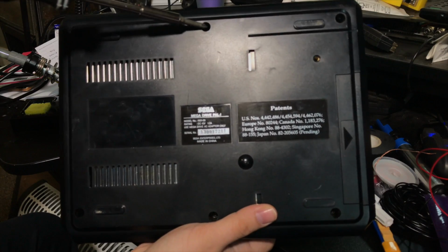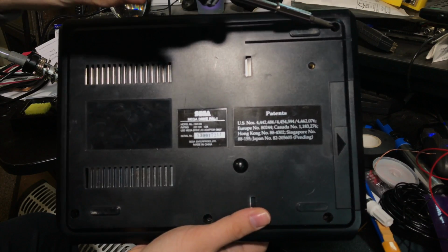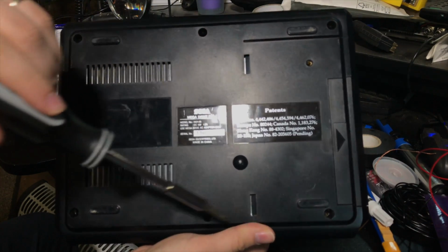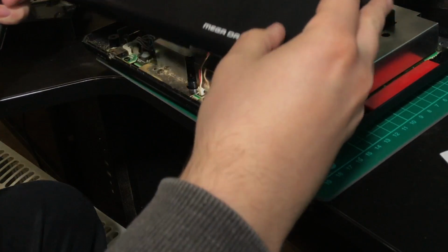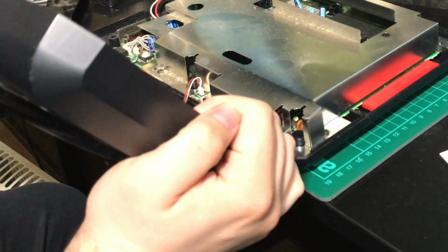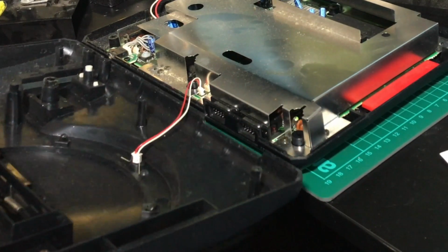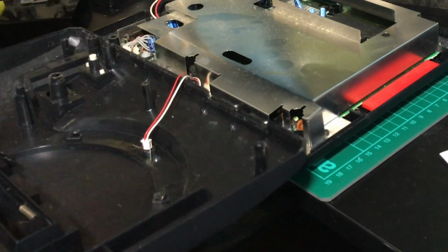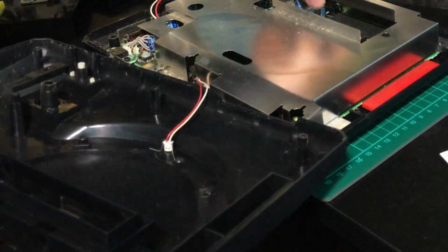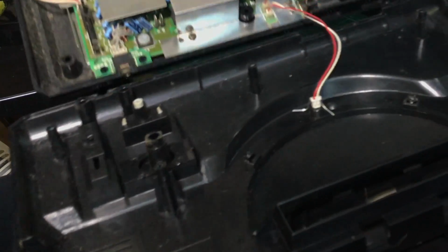So, open up your Mega Drive by turning your console upside down and remove these 6 screws, and do not forget to put those screws somewhere safe. You can now remove the shell, but be very careful as the top and bottom parts of the console shell will be connected thanks to the power LED. You can separate the two parts by bending the LED's legs up straight and slide the LED assembly out of the casing, but it's not completely necessary if you're careful.